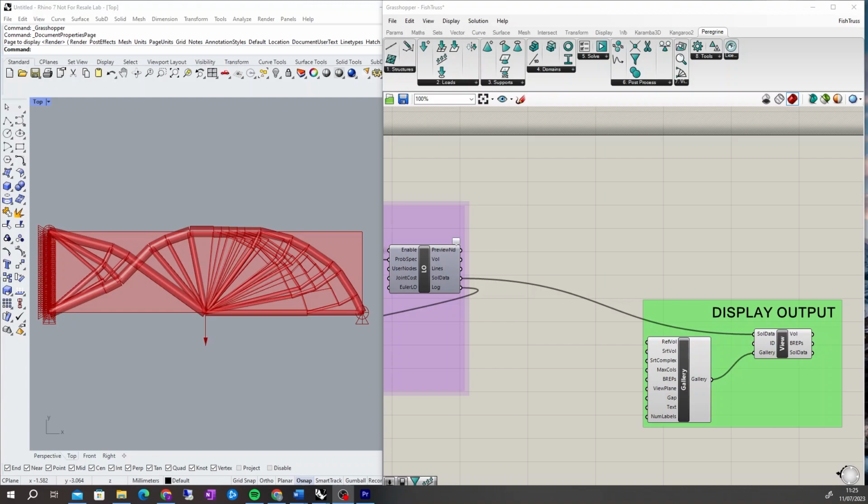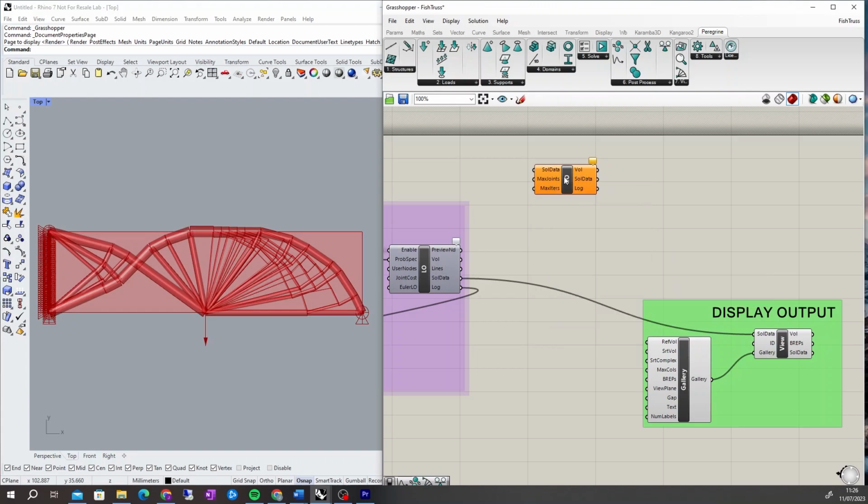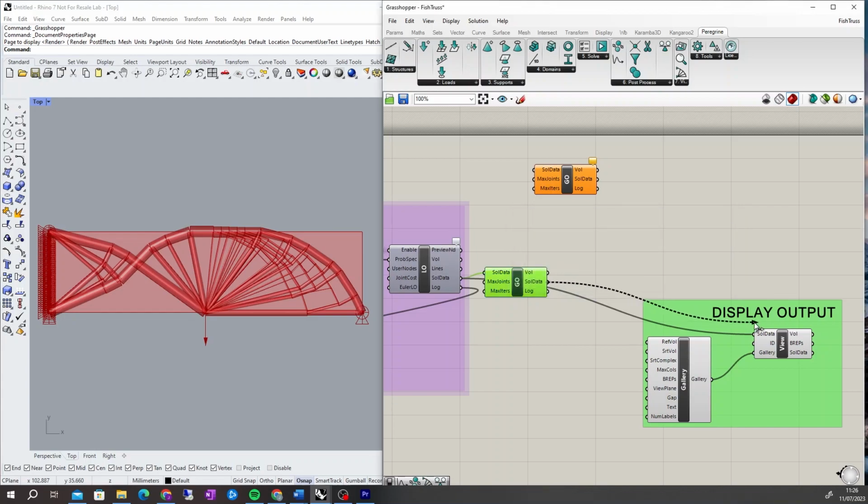This is the raw solution calculated using the layout optimization component with a high nodal density. Post-processing components can be connected using the solution data inputs and outputs to the components. Now I'm going to use the geometry optimization component to allow the nodes to migrate away from their Cartesian coordinates. This will likely reduce the required material volume and produce a slightly more simplified layout.